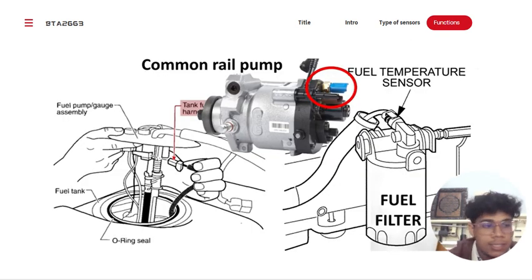The fuel temperature sensor is most often located somewhere at the fuel tank, often as part of the fuel pump assembly. Sometimes it can be found somewhere else along the fuel line. The information coming from the fuel temperature sensor is only used to further improve the injection accuracy in order to meet stringent emission standards.